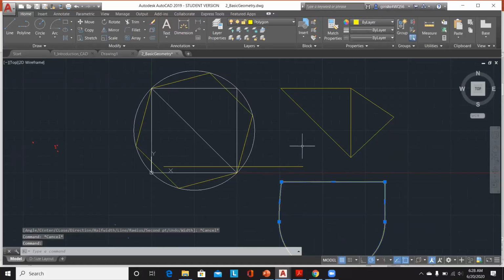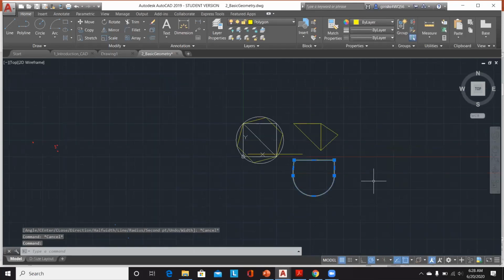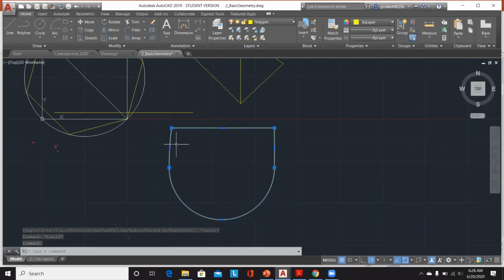So you can see that the entire drawing that you created has appeared in the form of a single series of objects, a polyline object, which you can control the length of, or you can control the angle by snapping to the object. So Polyline offers you the feature that lets you create a series of lines that are interconnected to each other. So why is this feature important?